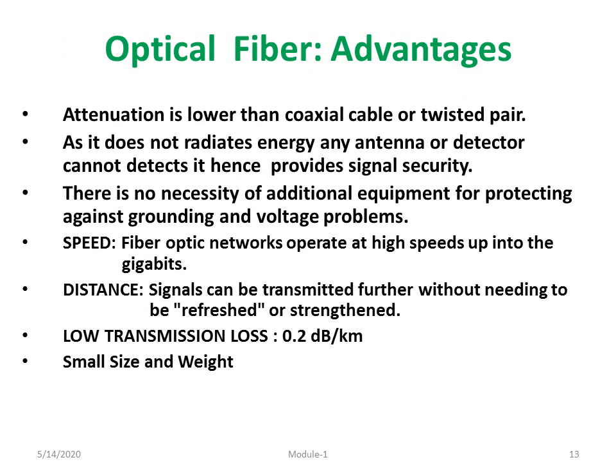And attenuation is lower than coaxial cable because of the optical fibers and the principle of transmitting the data with the total internal reflection concept. There is not much loss in optical fiber, and because it is made up of plastic or polymer or glass material, an insulating material, the interference is very less, and there is no power drop or heat dissipation in the fiber. If you compare copper, it has some resistance. Because of the resistance, some voltage drop takes place, and power dissipation takes place as heat, but here there is not much attenuation. That's why it can be used for a longer distance without any repeaters.